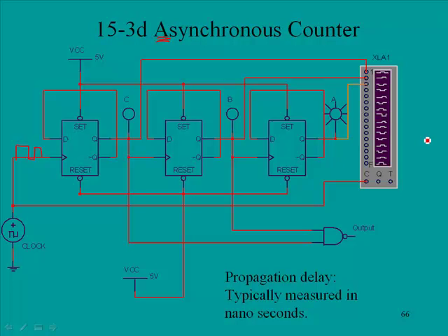They work well. There's really not a problem with these, except that at higher frequencies they can become problematic, and it's because of something called propagation delay. Your text mentioned it earlier. I didn't mention it then, but I will mention it now. Propagation delay is the time that it takes a signal to move from the input to the output. Typically we think of that as being instantaneous because it is so rapid, but actually it does take an amount of time. Typically it's measured in nanoseconds.